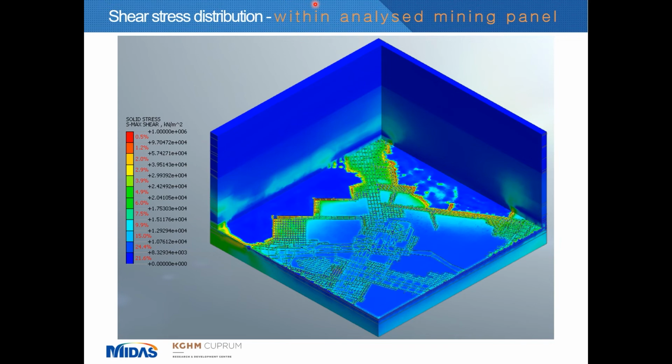But nevertheless, for technical reasons related to the operating system which is used in our mines, high values of shear stresses might appear, especially in some areas of the model. And the location of these stresses allows us to take appropriate preventive measures to relieve them, for example, to provide some relief blasting, etc. And of course, in extreme cases, you can exclude chosen workings from use. And we can see that the highest values of shear stresses may be observed in the direct vicinity of the mining front, and in the area of backfilling. So these results of modeling in general fit the situation which we observe underground in reality.